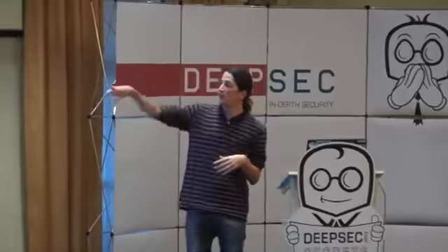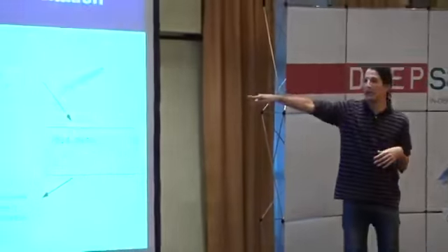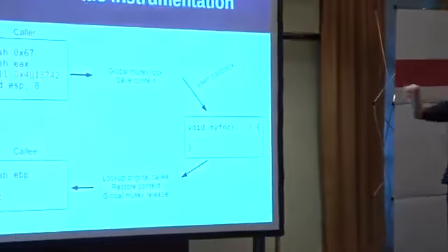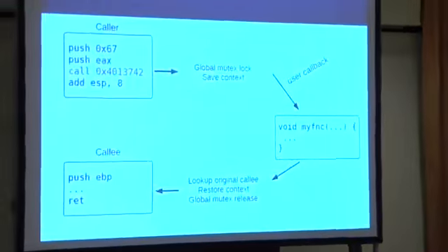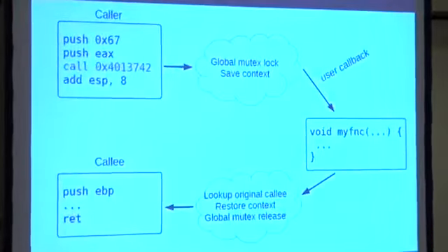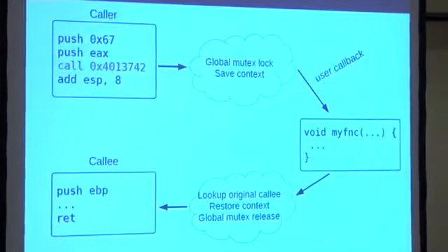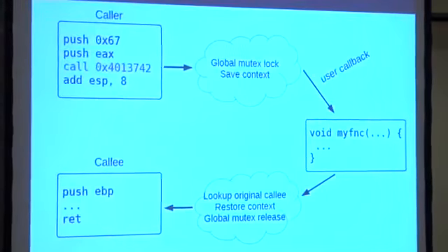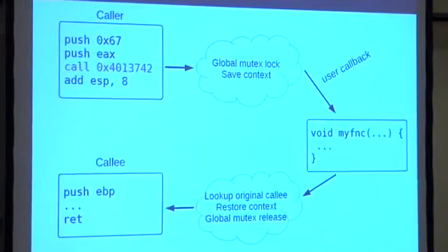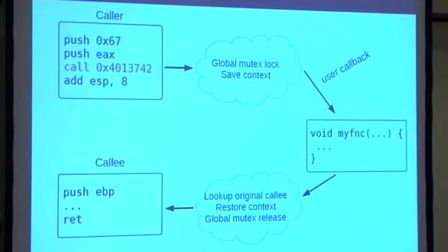So there you see what stands for a basic block of the original software. That would be a piece of the original software. We see a call function, and as I said, we patch. We remove the immediate there and put our own immediate. So whenever the application reaches that point, it jumps to a controlled piece of software we wrote. And in there, what happens is that we do a global matrix, because it's the easiest way to implement this. So we just do a matrix.